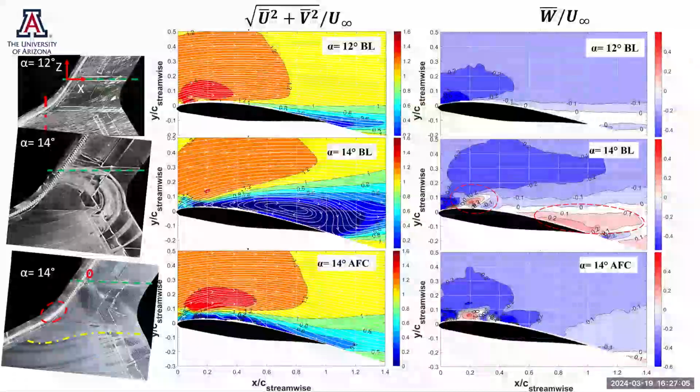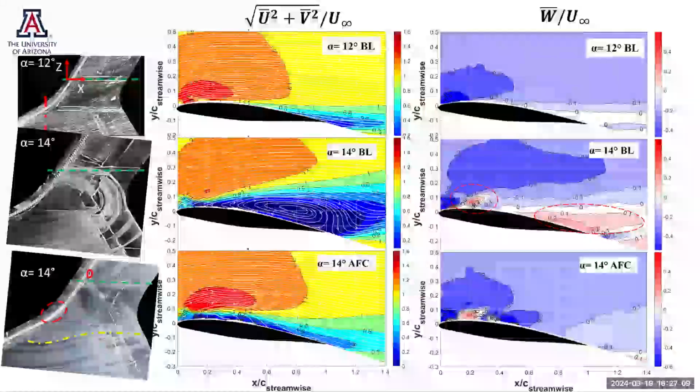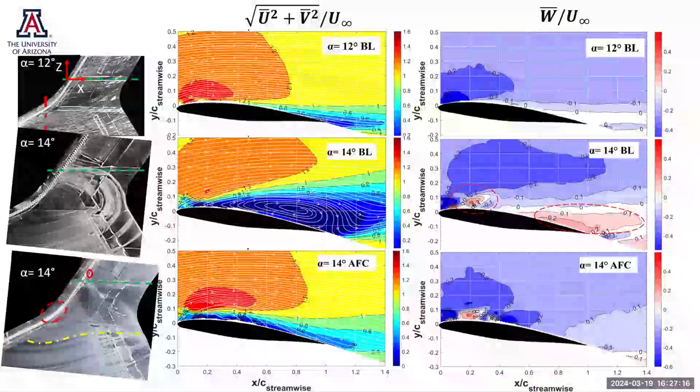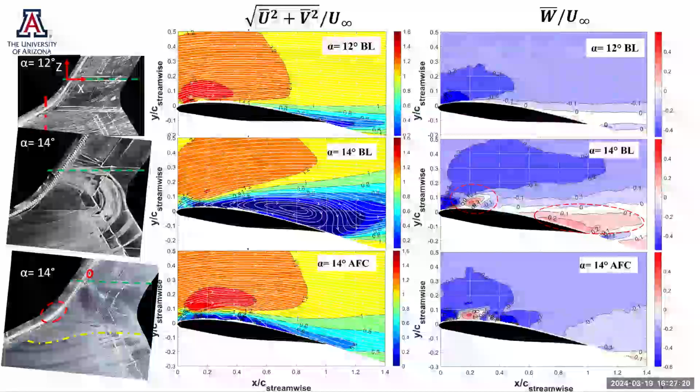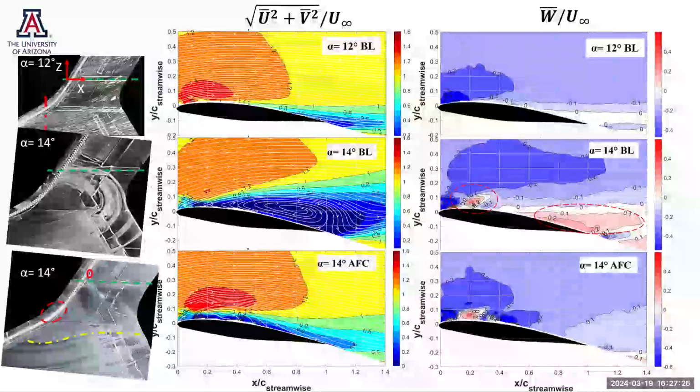The jet intersects with this leading edge vortex liftoff process, hence restricting this process to a smaller region. And you can see the inboard streak line, instead of curving outboard like how it was, just goes streamwise downstream.